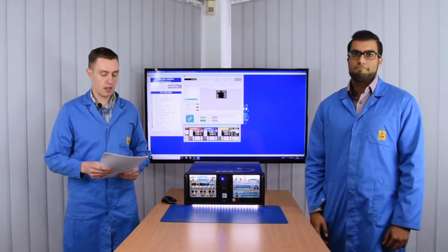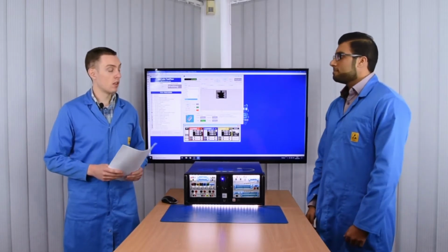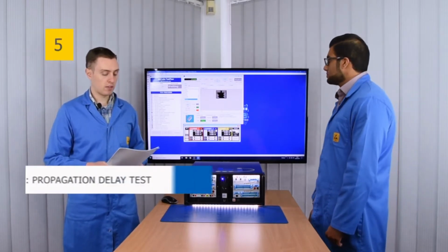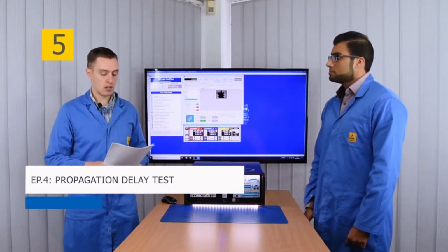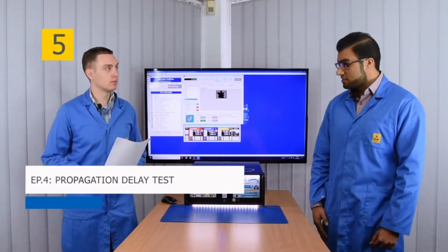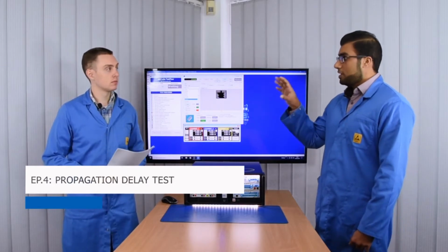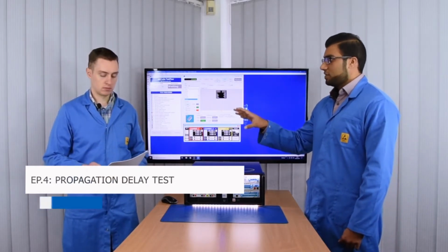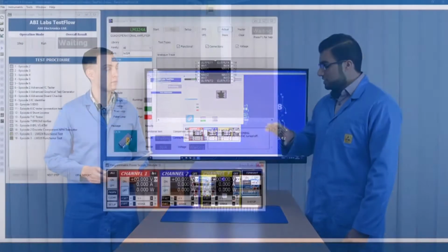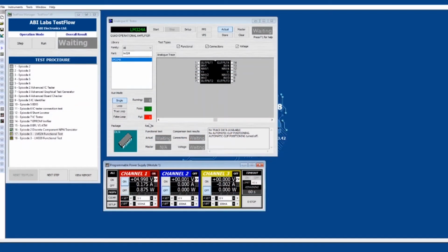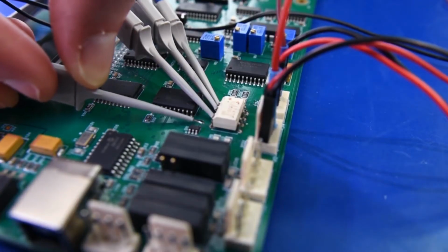Okay, fantastic. And in the same episode, we introduced the MIS4 module. What tests do we do with the DSO, AWG and Y? Okay, fantastic. So in that episode, you explained the DSO, as well as the waveform generator. With the waveform generator, we injected a square signal into one side of the optocoupler, which was on the PCB that we had in front of us at that moment in time.